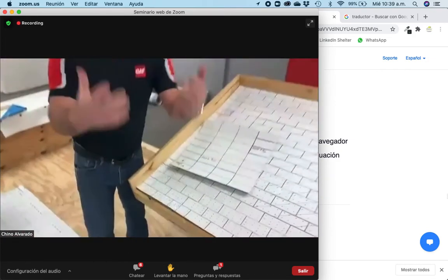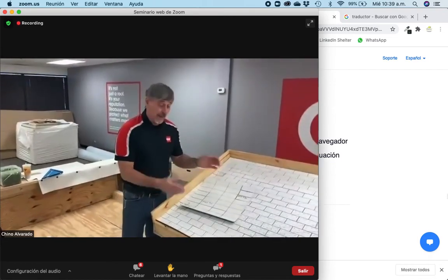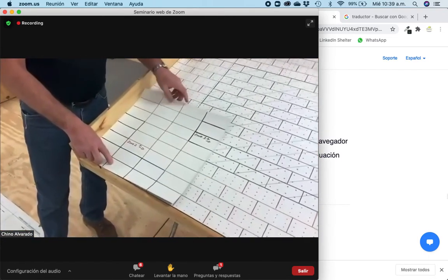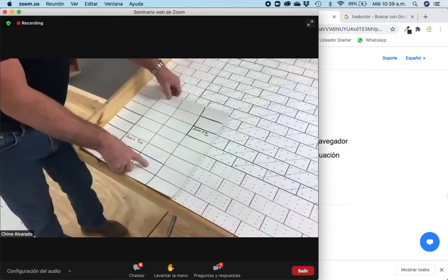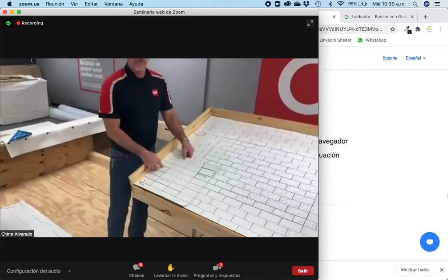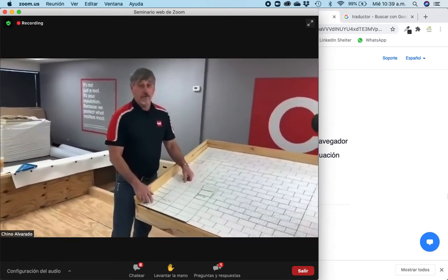Again, this is just a suggestion for you guys in the field. Stagger off your bottom layer. Run your full 4x8 sheets. Now, am I longer? Sure, I'm long. I'm 24 feet this way, but I'm still 20 foot this way. And we have our L, if you will.